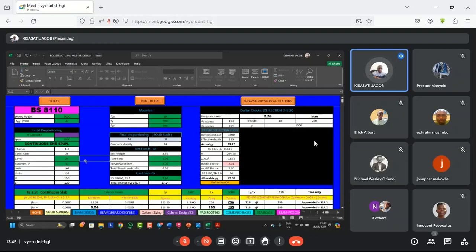Now, which table is giving you the biggest value? For that one, you just find out we have 20 and 25, and we always use 25. So for this one, I can assure you we'll be using 25 for slabs. Because in the field, we always use, for the bar size, 10 millimeter dia. So for this one, we just assume 10 millimeters.